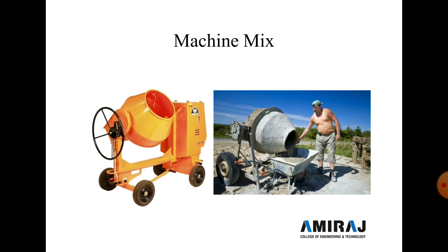Then we add the water and mix thoroughly. Now rotate the mixer pan for 2 minutes to get very well mixed concrete, and then tilt the pan and collect the mixed concrete in a bucket. See figure number 2, or photo number 2.